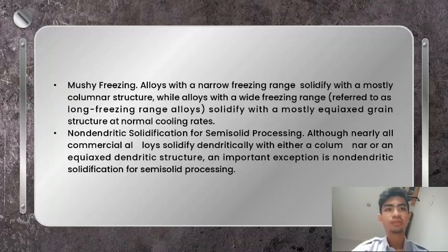Non-dendritic solidification for semi-solid processing. Although commercial alloys solidify dendritically with either a columnar or an equiaxed dendritic structure, an important exception is non-dendritic solidification for semi-solid processing.